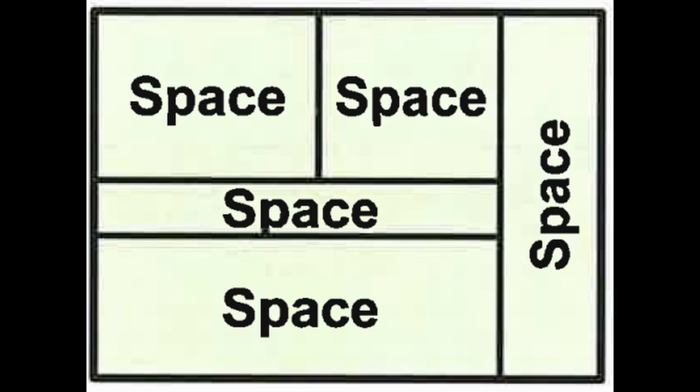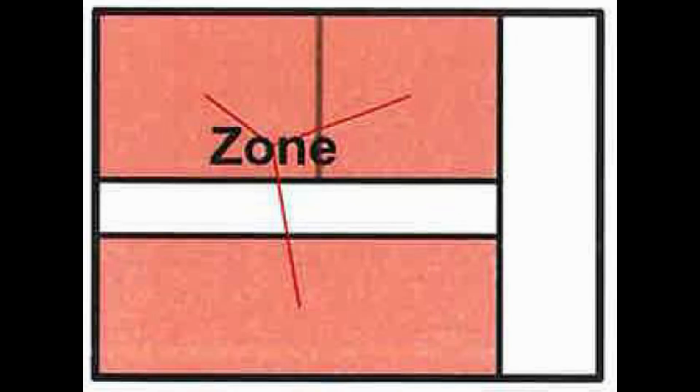Spaces are essential for HVAC sizing and energy analysis. Finally, zones group multiple spaces together. A zone might represent all the rooms served by a single air handling unit, or a group of spaces that share the same environmental conditions. Zones are critical for heating and cooling load calculations.